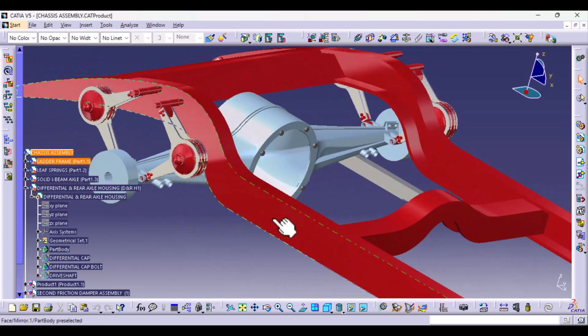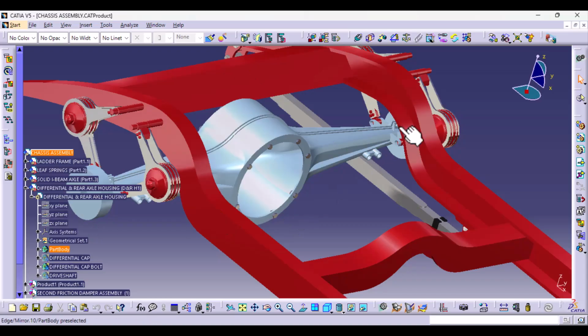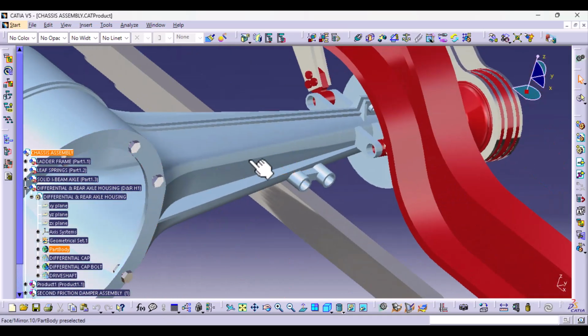So it's just a matter of making sure that the subsequent geometry that comes after the part you're editing is constrained to the original part. And the best way to do that is to constrain the sketches. So I hope you have learned something today.